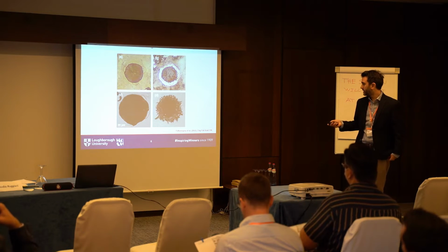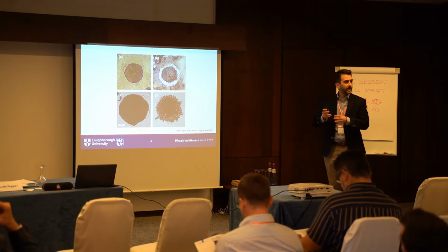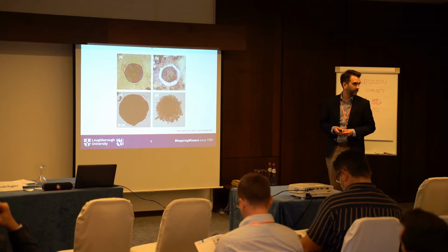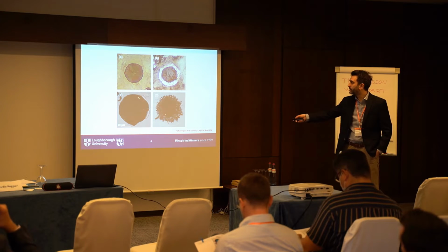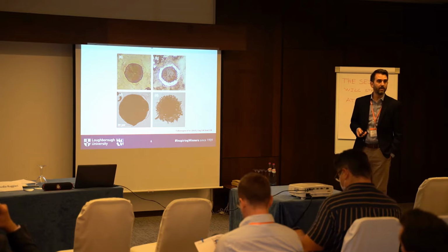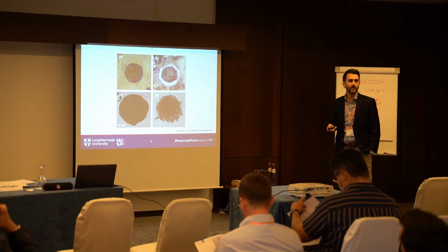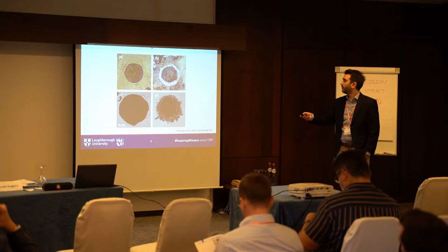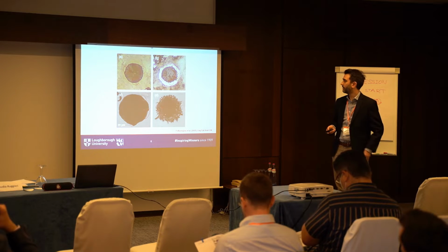Very recently we published this experimental and modeling study, where we applied cyclic thermal load only, no mechanical load. And still you could see some decohesion, and some fracture of the graphite after 2 or 3 cycles. I wouldn't dare call this fatigue. One more thing to keep from this slide is these rings around the inclusions. They will come in handy in a moment.